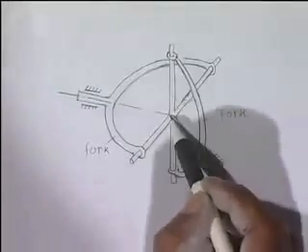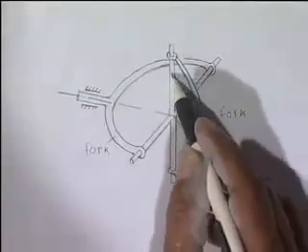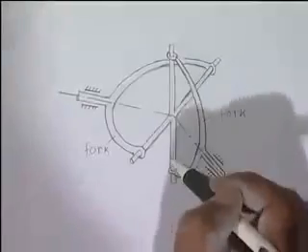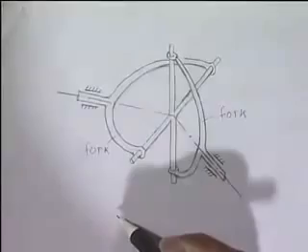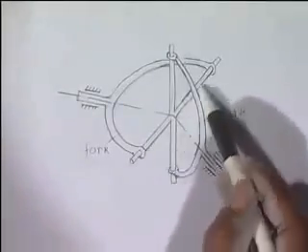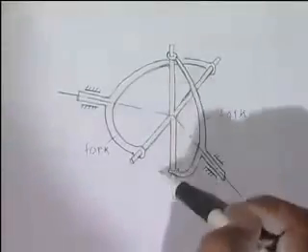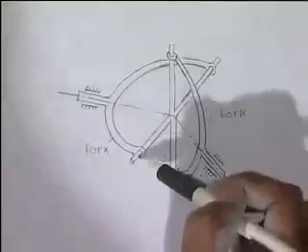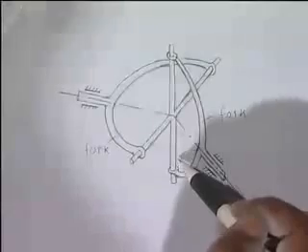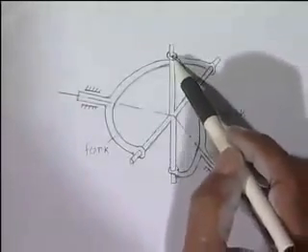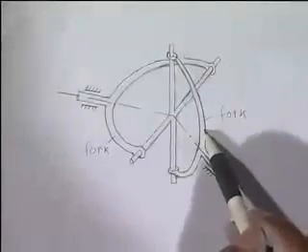And this is a cross arm. The angle between these two parts of this cross is 90 degrees. This is vertical, this is horizontal in this configuration. This horizontal part of this crossbar is mounted in two bearings in this fork. Similarly, the vertical arm is mounted in these two bearings carried by this fork.